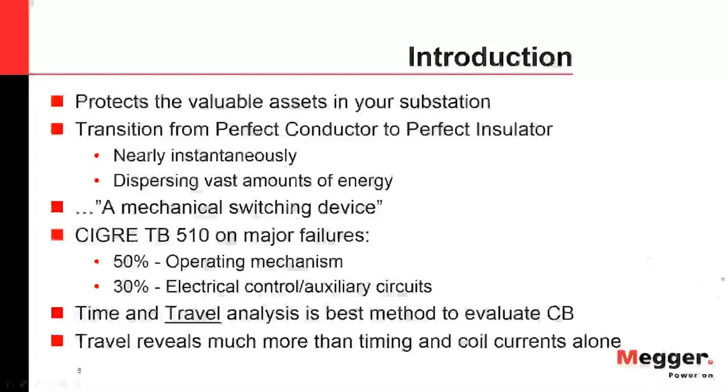So just generally on circuit breakers, sometimes they're neglected, and they shouldn't be, because they protect the valuable assets in your substation. You don't want your $5 million transformer to blow up because you didn't maintain your circuit breaker. So you want to make sure that these things are in tip-top shape, because the weird thing about a circuit breaker is it'll sit there idle for, it could even be years.